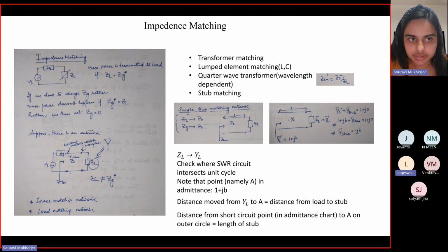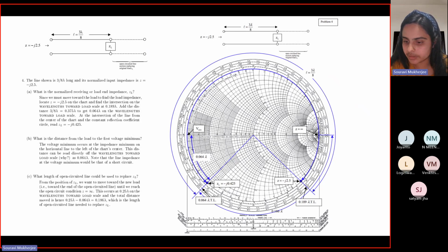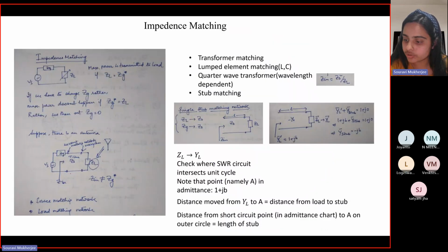There are two things. First, if you have some impedance on the generator side and then a load, this is the relation, and it holds when you have maximum power transmitted. So this is one condition. Now, what you are saying is there is no reflection from the other end, so that means the impedances should match. If your Z0 is provided and you want to find ZL, then your ZL should be equal to Z0 at that point so that there is no reflection.